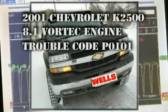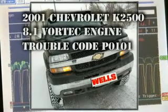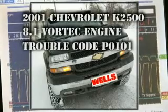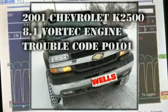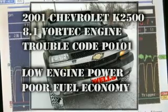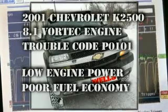The check engine light is illuminated with a trouble code P0101, which means the MAF sensor frequency signal is not within a predetermined range of the calculated value for more than 8 seconds. The owner also commented the engine power seemed low, especially on acceleration, and his fuel economy had dropped.